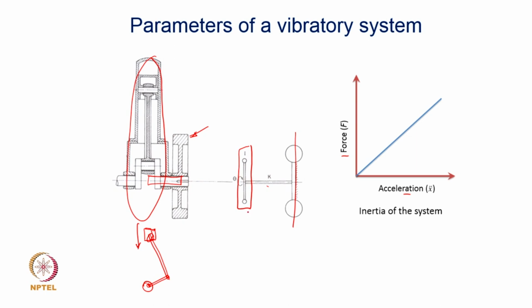So, the inertia property of such an IC engine mechanism, or connecting crank, connecting rod and piston mechanism, is not going to be a constant, although we can integrate the kinetic energy over one cycle of rotation and equate it to a constant I value, which is going to be an equivalent constant I, but strictly speaking it is going to be a function of angle, and therefore it is not going to be a constant value as such.